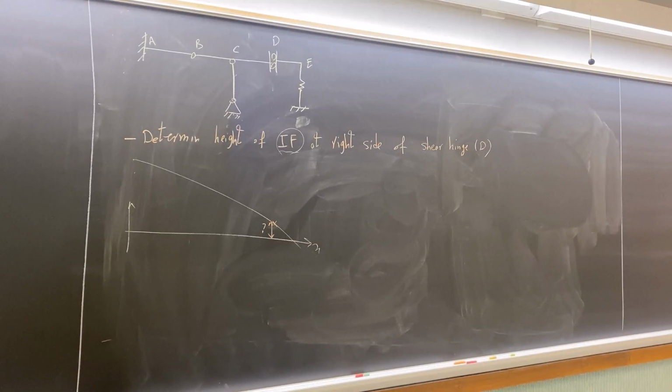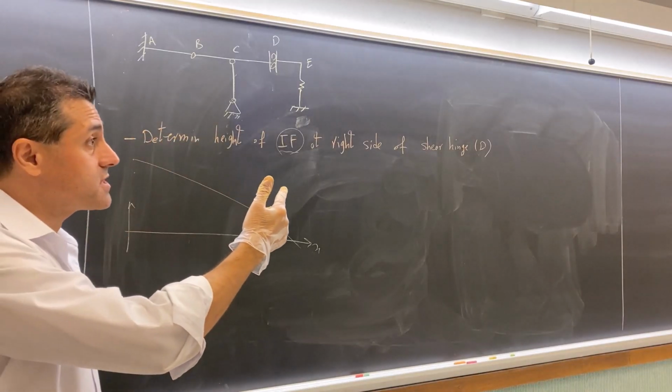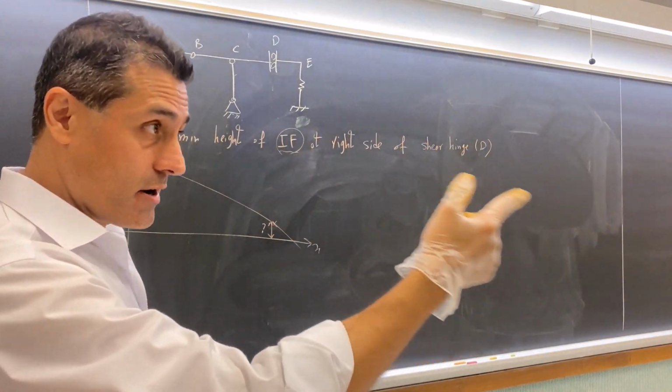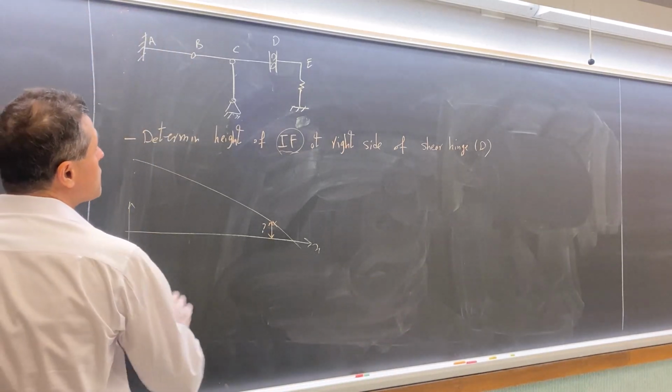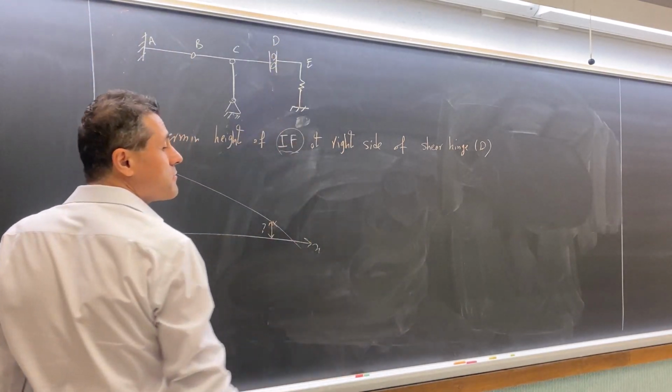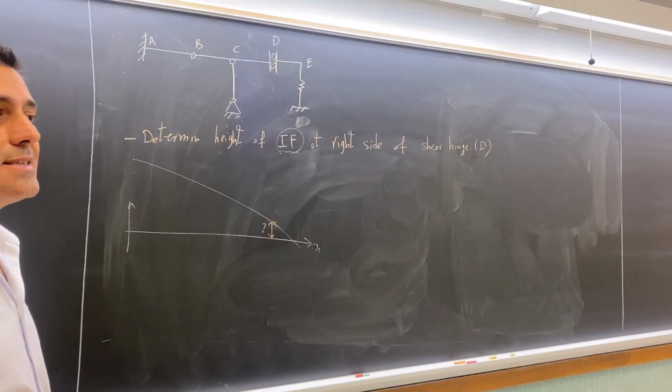What method do you propose? You already know the concept of influence line. And in the previous example, you learned how to find the amount of influence line for different points. Remember, you found the influence line for points A, B, C, and connected them together. So now you just need to find the amount of influence line for point D.